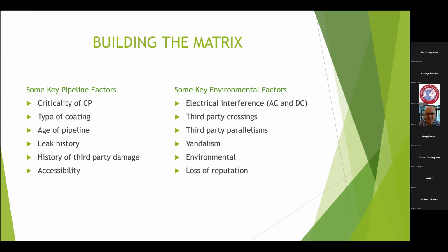Does it matter if it's not applied for a week or 2 weeks or 3 weeks or 4 weeks? And very often the answer is no, because if it's a well-coated pipe, you can survive, and there's no electrical interference from railways or anything like that. You could well survive without any worries for a couple of weeks.